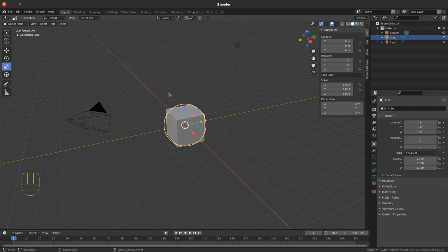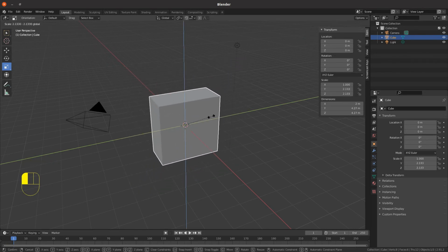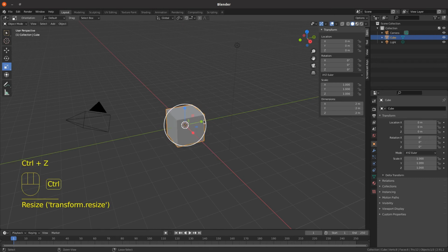You've also got the option to scale it just on 2 planes. So if you want to scale it on the XZ axis, you would press the square that is separate from the axis markers, and this constrains the scale to the X and Z. Control Z on that to bring the scale back down to 1. So there are your scale options using the scale widget.